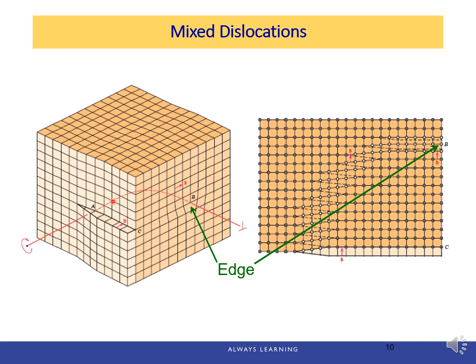And at point A here, the dislocation is a pure screw dislocation. But for the regions in between, where there is curvature in the dislocation line, the character is mixed edge and screw. So the lattice distortion that is produced away from the two faces is mixed, having varying degrees of screw and edge character.